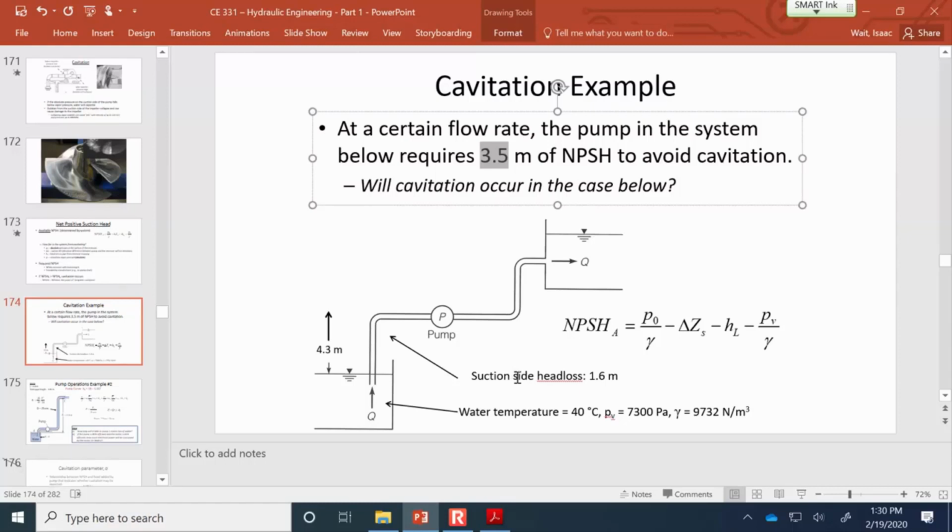If you have a small diameter pipe, you have more head loss than a large diameter pipe. If you're perceptive, oftentimes you'll notice that on the suction side, the hose is a larger diameter than on the discharge side of a pump. I've seen that in lots of lab scenarios where they use pumps to draw water up out of a storage tank. They use a large diameter pipe on the suction side because a lower velocity means less head loss, and therefore less risk of cavitation.